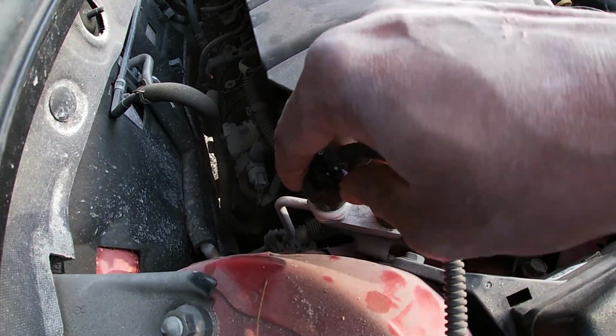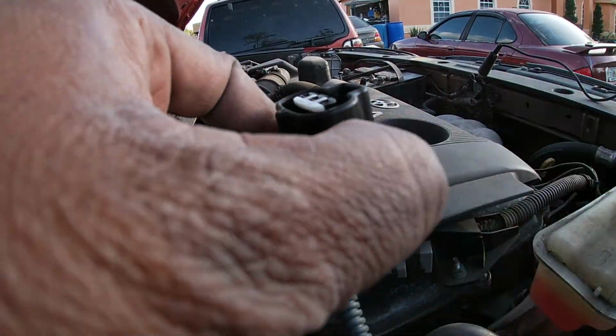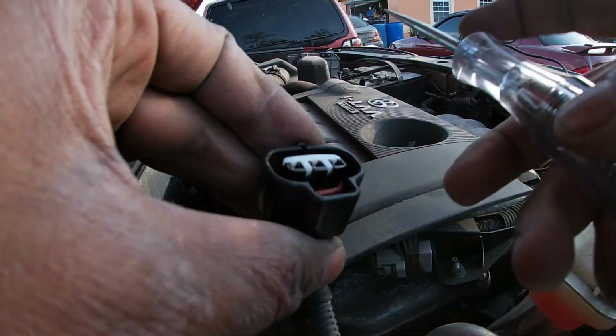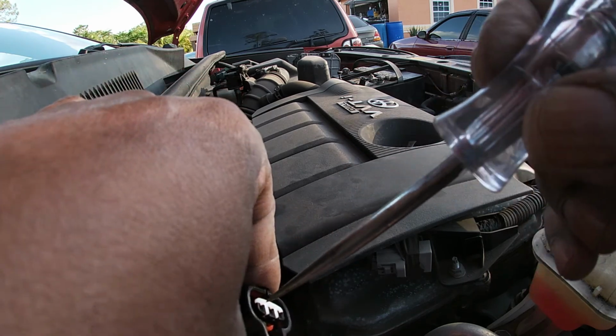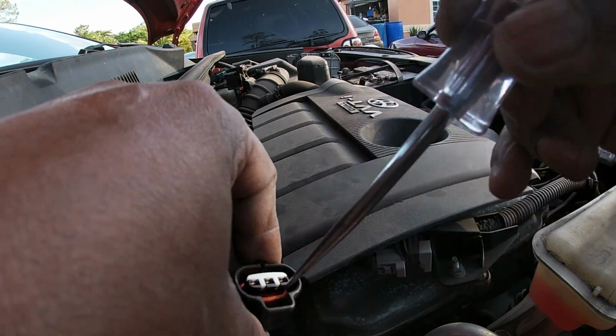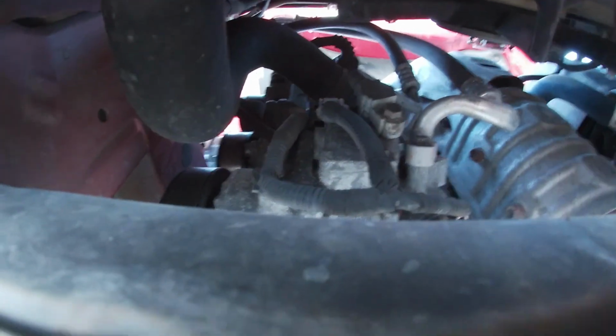What you're looking at right here is where the pressure switch is located. I went ahead and disconnected it, and I got a test light, and I'm just checking for voltage, making sure I'm getting some kind of voltage through. Exactly the amount of voltage that's needed, I wasn't too sure, but I was just checking to make sure I had power going there, which I did. I think it's probably about 5 volts. Most of these things are about 5 volts. So I moved on to the sensor.